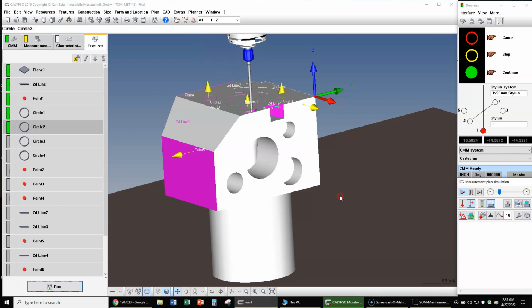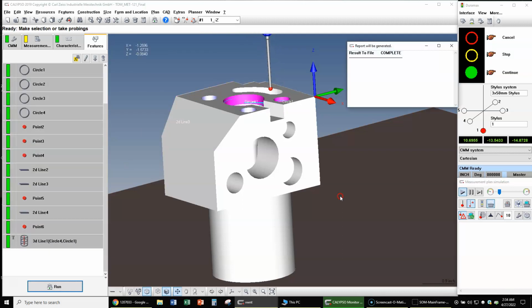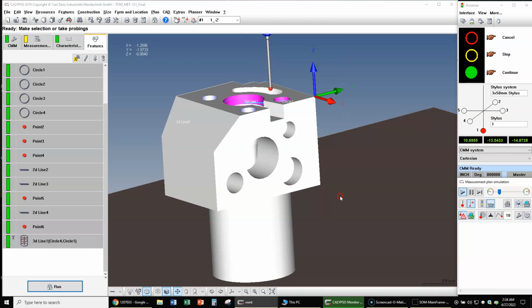Now, I already noticed some problems here. Did anybody else notice some problems? We missed the step. I was going to say we didn't check if their clearances are all in +Z. Yes, very good. We did not check our clearances. I'm noticing another problem here where this program is not path efficient, and the clearance plane for that last feature was -X. That one was -Y. And the retract for that one is going to potentially crash into the back wall. So I found all that out from the simulation. That's the level of detail you should be paying attention to.